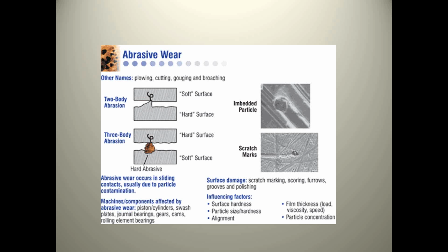It's got scratches. In this case, you've got a particle embedded in the metal. So again, this is what's happening to your components and the reason your components are failing. But these are things you can't see with the naked eye. This was a bearing surface looked at under a 100 power microscope, so you can see what the difference is.